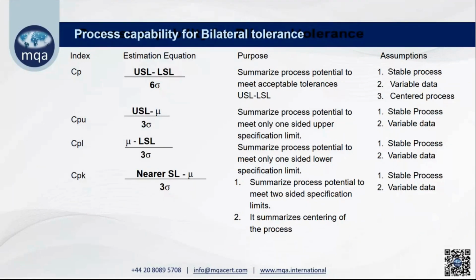The shaft has to be larger, so the shaft will be 50 mm plus 25 micron. So the shaft will be on the higher side, the ID on the lower side. So we have this unilateral tolerance, one direction tolerance. And bilateral we see every time, 10 plus minus 1, 20 plus minus 1. 20 is the mean, it can go up also, down also, right?